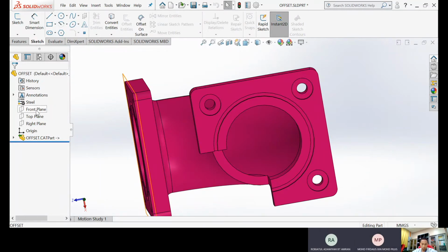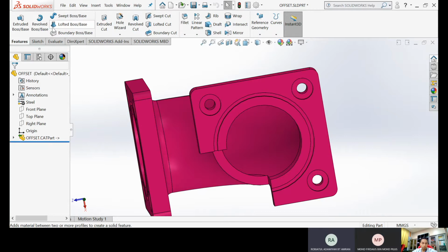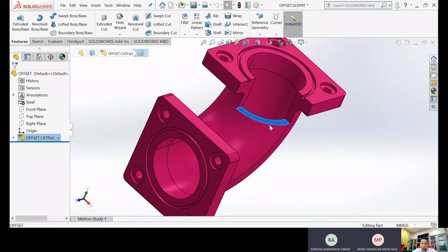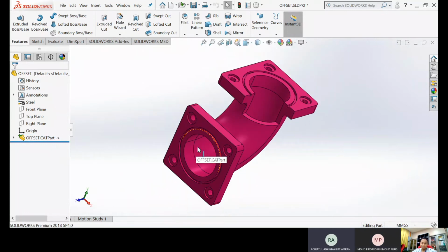Noise can be removed by area if the area at a large part or small part is different from the main part. By turning the removal corridor all the way up, it takes anything that was below the main part of the STL edit. Next section is the extraneous data removal. Just rotate the part and only focus on the area selected. For creating surface, the automatic creation is the best choice for the area selected, while guided creation is going to be quite a bit more work. Then, by using polygon selection, remove all the unnecessary information and make sure to have some overlap extra area.